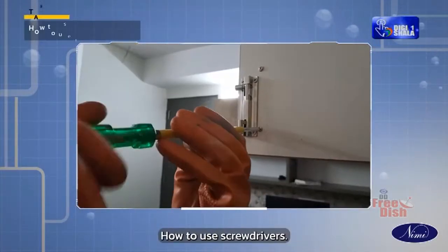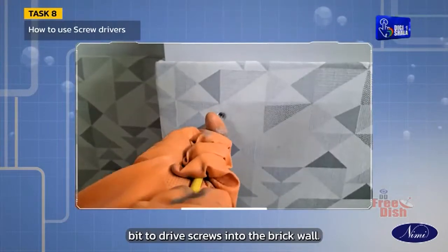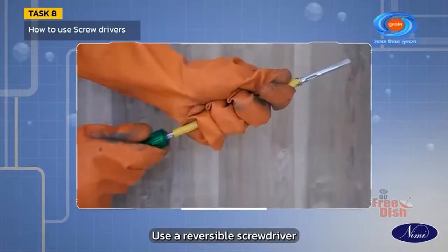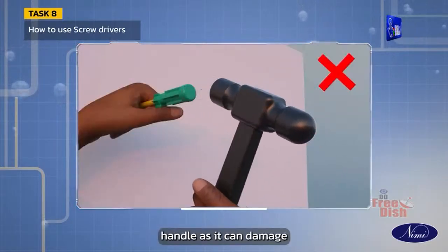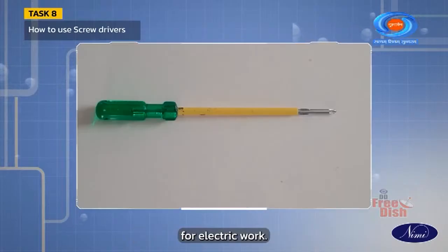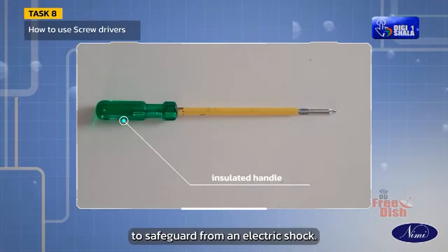How to use screwdrivers. Use the appropriate screwdriver bit to drive screws into the brick wall. Use a ratchet for quick and easy screwing operation. Use a reversible screwdriver that has a star head and a flathead screw. Never hammer the screwdriver handle as it can damage the handle and affect its usability. For electric work, use a screwdriver with an insulated handle to safeguard from an electric shock.